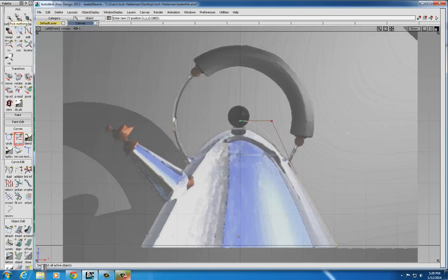So let's go ahead and do that. I'm going to first select nothing, but this time instead of choosing Pick Object, I'm going to go further down on the Pick menu and choose Pick CV. This will allow me to pick individual CVs along the curve instead of the entire curve itself. Now I want to move those points down, so I'm going to go to the Transform menu, choose the Move tool. Notice they're still selected.